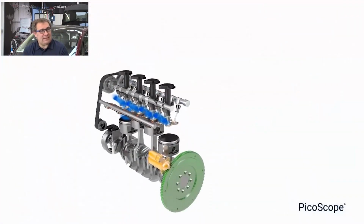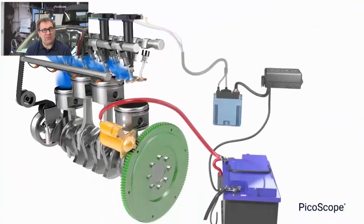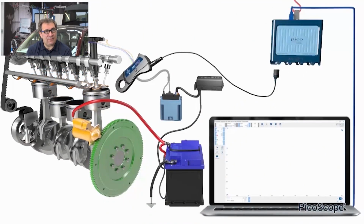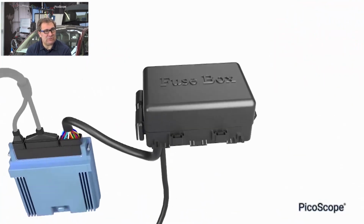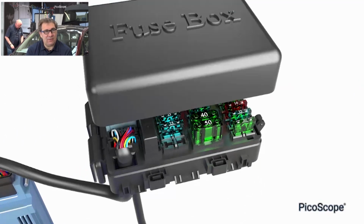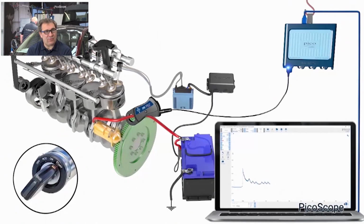So in our short animation, this is one of the animations that's in our app, so our top 10 tests of working with PicoScope. So single channel test, so it's the same connection, but only one channel as we just did with the battery test. We don't want the vehicle to start, so that's why we're removing the fuse from the fuel pump. So we're running this on cranking.